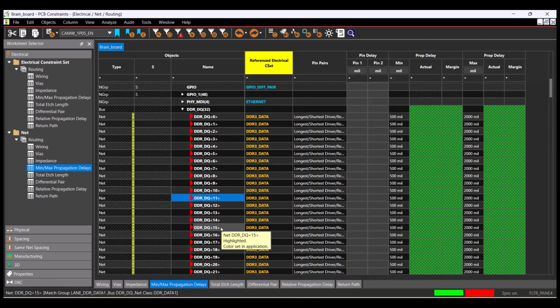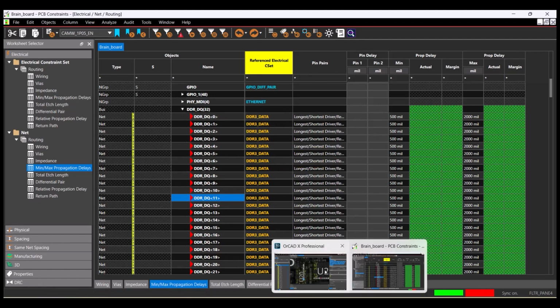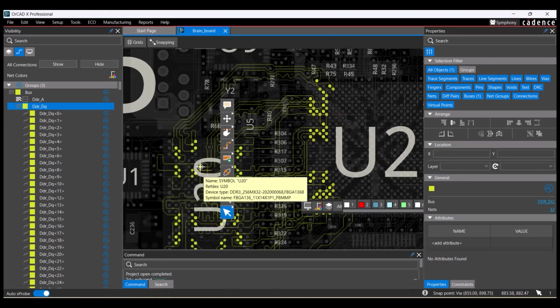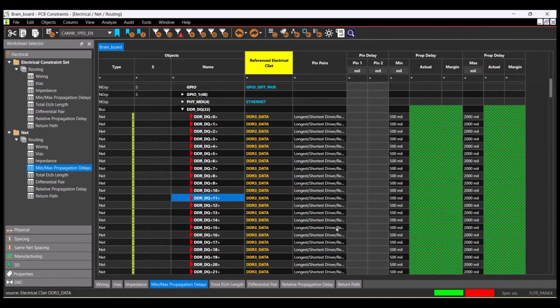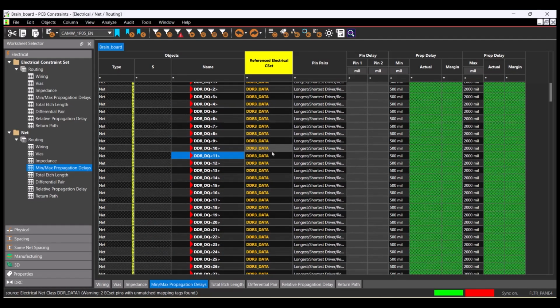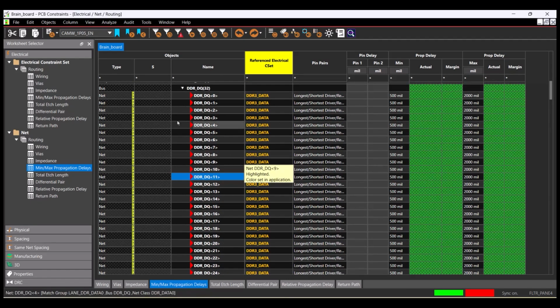So hopefully you're seeing the power of doing that. You are not just defining how one signal is going to work. You understand that all those signals are routed on the same PCB, same stack up, same everything. So you are creating a constraint set and assigning that constraint set to the entire interface. Once you get that constraint set assigned to the entire interface, the electrical field solver inside of Allegro X and OrCAD X is constantly going to be running, verifying these rules while you're routing your design. That's the power of using Topology Explorer to create and verify electrical constraints.